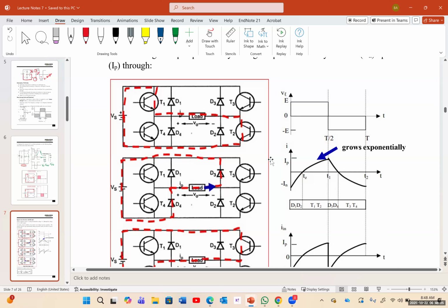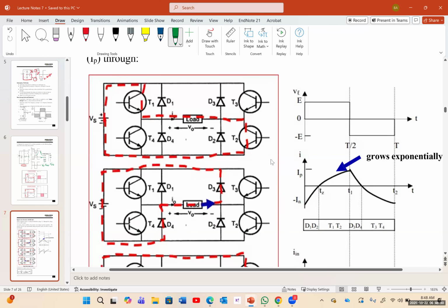So this is a real world example of an inverter. For the switch, we use a transistor. This here is using a BJT transistor, and we use a diode for the freewheeling to protect the transistor. Exact same thing that we had for the buck boost converters. We use a diode over there. Here we use it over here as well as for the switch.